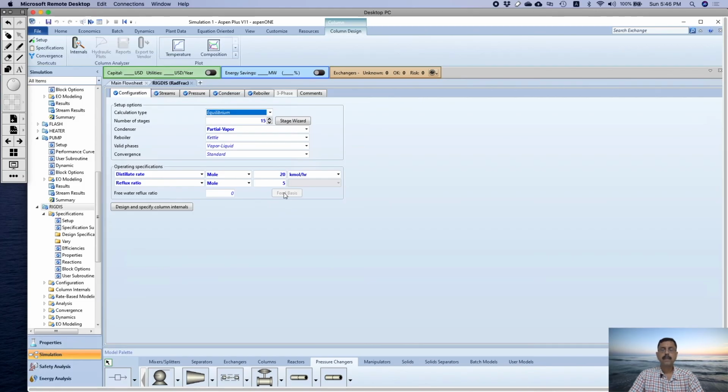So if your reflux ratio is decreased, distillate quality composition should be decreased, right? But if we need to keep the distillate composition intact, then we need to increase the molar enthalpy of the reboiler, right? So that is the logical conclusion.